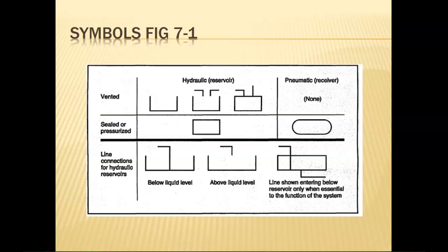Well, the whole point is that in any tank or reservoir, so let's say this is my tank and this is my pump. I don't want my pump sitting down here because that's where all the garbage collects, right? Because what does sediment gradually like to do? Settles to the bottom, right? Just like in the ocean, where does all the sand sit? At the bottom, right? So we don't want to be sucking up nasty crud into our system because that's going to tear our system up really, really fast, right?